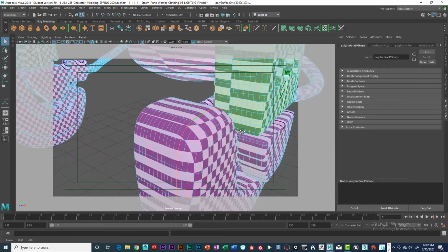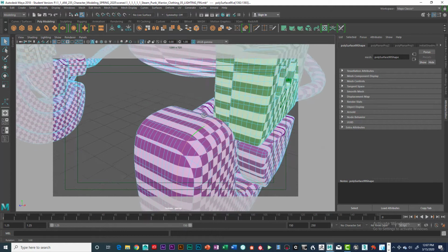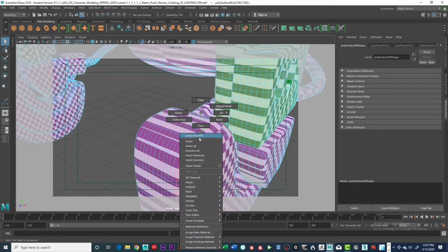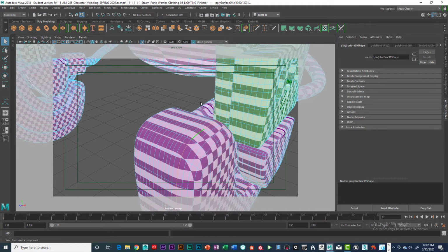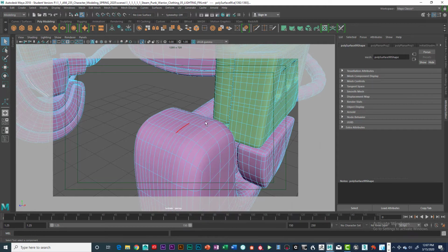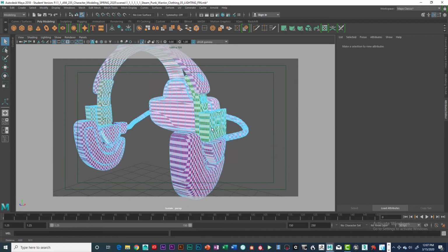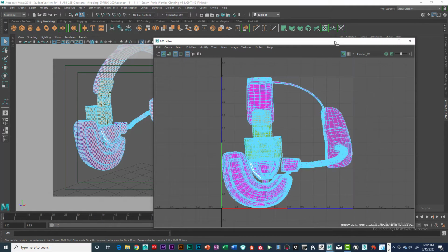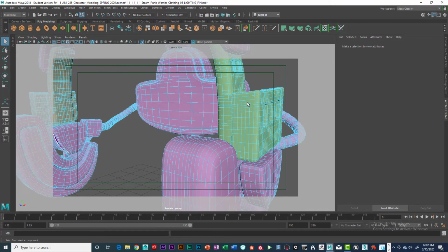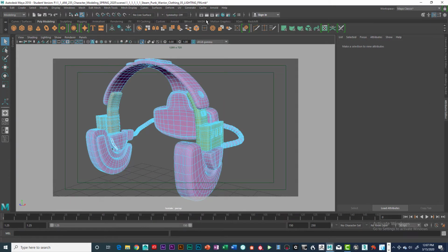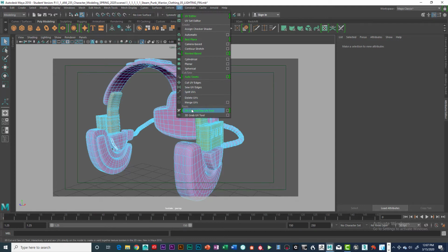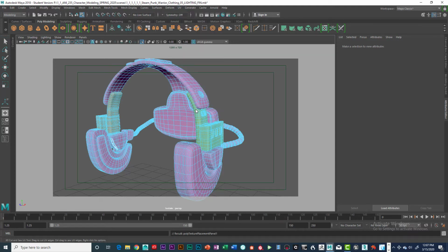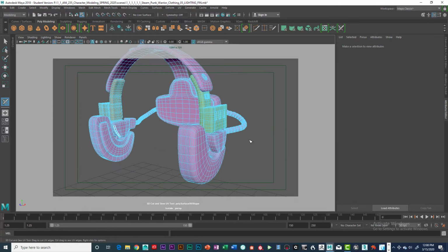And you can see we need to get into the seam mode. To do that, I'm going to click on edge mode again and click off. So I'm in edge mode. You can see I can turn this off, so get rid of that so it doesn't get in the way. And we're in edge mode now. So what I want to do is go to UV, 3D Cut and Sew UVs. It says drag to cut, control drag to sew.